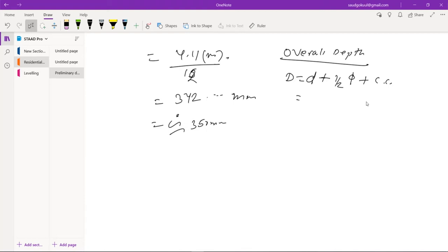If, while designing the building, we find that this size is not sufficient and the beams will fail, then you can increase the size, but for the time being you should start with 350 mm. Don't go with sizes like 360, 370, as that might be hard at the site. It might be surprising for the workers, because they are used to the usual sizes.